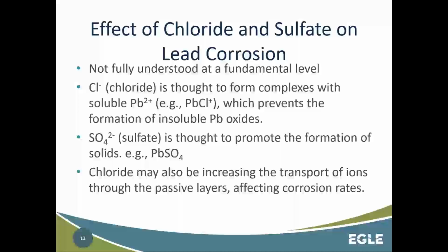So, chloride itself is at least thought to form complexes with soluble lead, which prevents the formation of insoluble lead oxides. Okay, so what that's essentially saying, soluble meaning it's going into the water solution, insoluble meaning it's going to stay as a particle that you can either filter out, or it'll precipitate out or form these compounds, where soluble will stay in solution and just float in the water column like anything else.